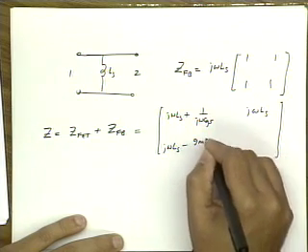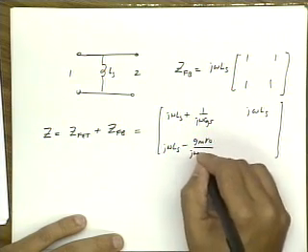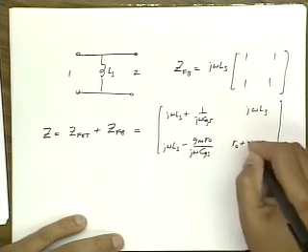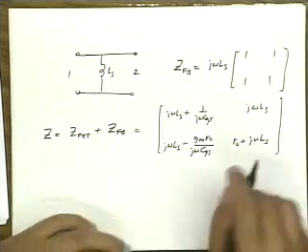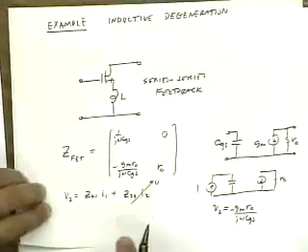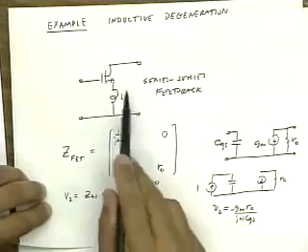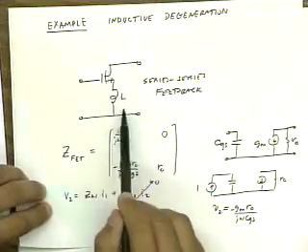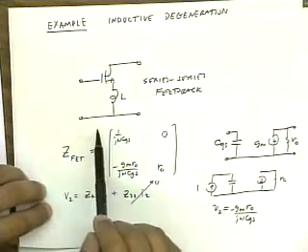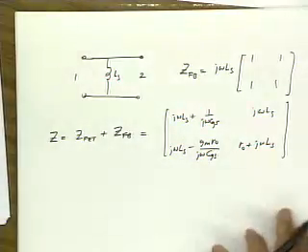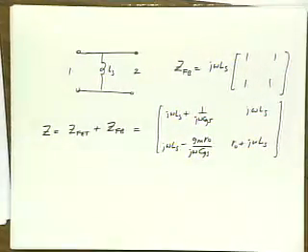And this again is something that you should, whenever you see a circuit that doesn't have feedback to begin with, and you do something to it that introduces feedback, you should worry about stability, especially at high frequencies. So just adding this element here clearly introduces a Z12 factor, because now part of the output voltage appears at the input. The output current generates an input voltage. Okay. So this is the overall Z matrix of the system.